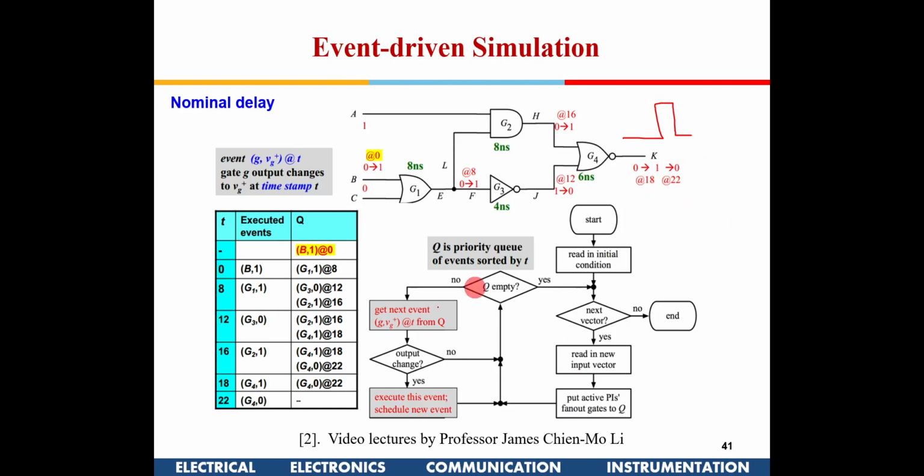Is there a problem with this thing? Because if I see the logical thing, it should be 0 only, but it is going to a 1 and coming to 0. So is the issue with testing, or is the issue something else? Anybody? Issue with timing delay, yes. Timing to a gate, correct. So testing is perfect. There is no issue with this logic which we are following.